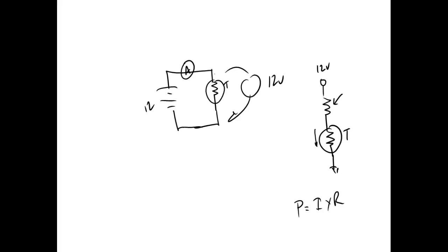So they put current through it. The current is going to create a what? A power. The power is going to create heat, which if it's an NTC thermistor, it'll cause its resistance to go down. Now what's going to happen when the water flows on it, it's going to do what? It's going to cool off, causing the resistance to go back up.